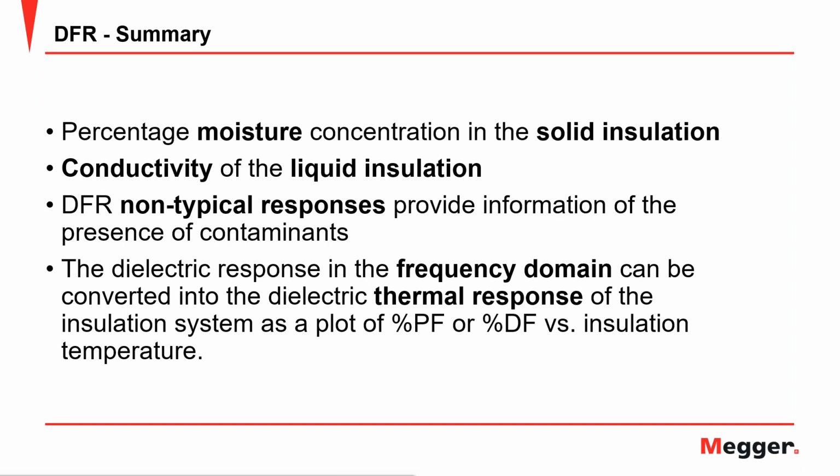And my question is, how many times has any of you listening to this webinar tested a transformer or a bushing at 20 degrees C? I'm pretty sure that it's very difficult to be at that moment exactly when the temperature was 20 degrees C. I'm talking about the insulation temperature. So you're always off that temperature by a few degrees or by a lot of degrees. No matter what temperature you're looking at, especially if it is above freezing, of course, you can do the individual temperature correction and have a very good assessment, right?